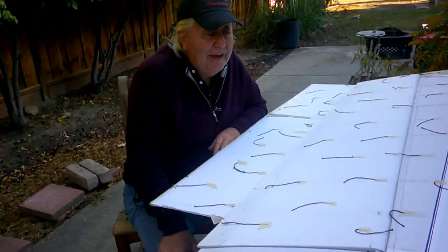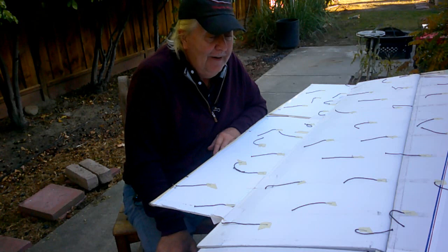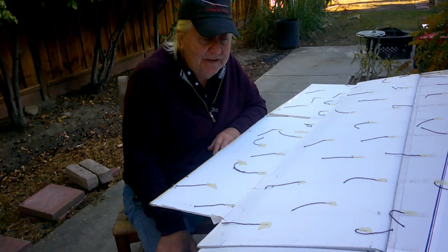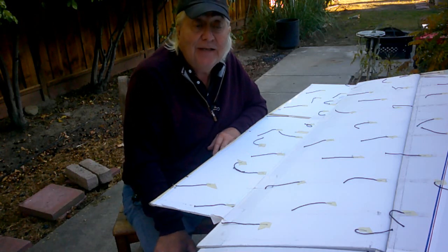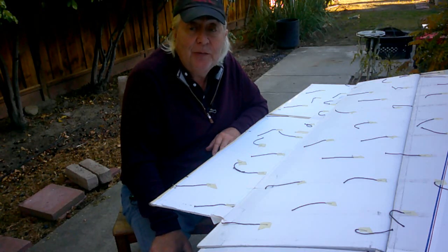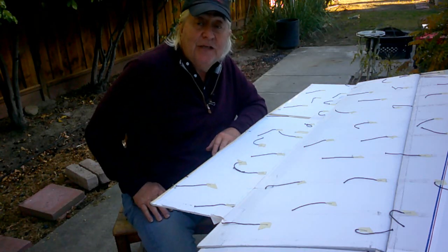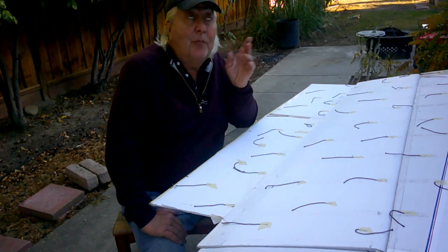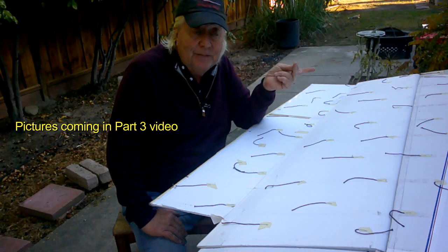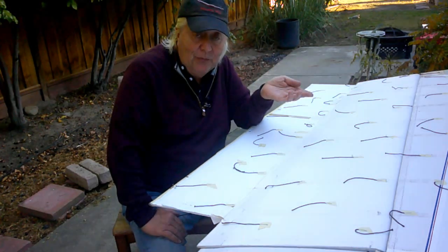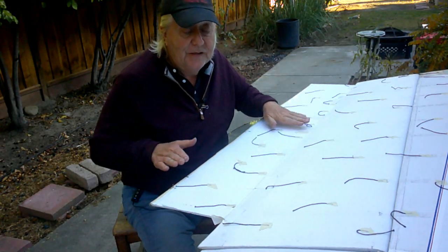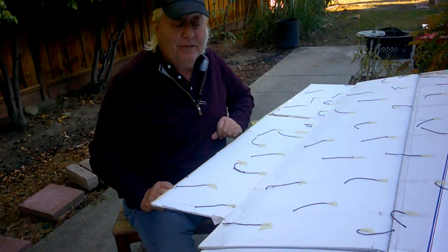So let's go back to what I was discussing before about the trip strip and keeping the flow attached on the elevons and where the problem really lies. So we have this bugaboo. It appears that, and I'll put pictures up here, the Impact hang glider, the Millennium, and the Mitchell wing, and my original wing all have elevons tacked on the trailing edge, and they all work.